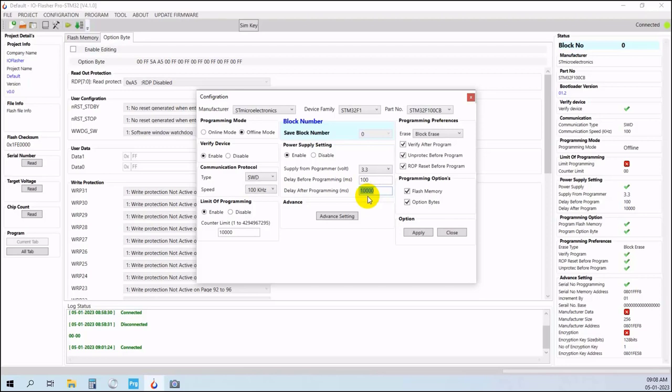So your target will be powered up. To reset your target, either remove the programming cable or use any switch if you have a reset switch on your target port. Because in many cases, especially when you are programming option bytes, your target cannot be reset through the reset pin. In that case you may need to remove the connector and reinsert it so that it can have a power on reset, and then you can test your features.